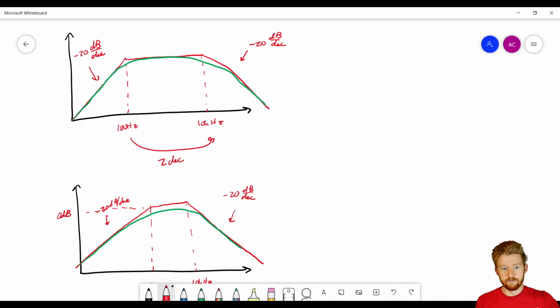Like I said, whenever you have those two cutoff frequencies so close together, it's harder to characterize what V out over V in is going to be. So just simulate the circuit to save yourself a little bit of headache. You can adjust things however you need them.